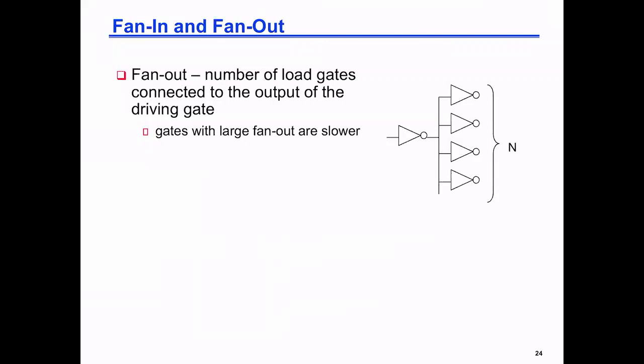And when we design the circuit, we start by asking what is the number of load gates that each gate can tolerate? For example, in a generation of, let us say, Power 7 at IBM, they say this library is fan out of 4, meaning a gate can drive at most 4 other gates. I cannot drive more.